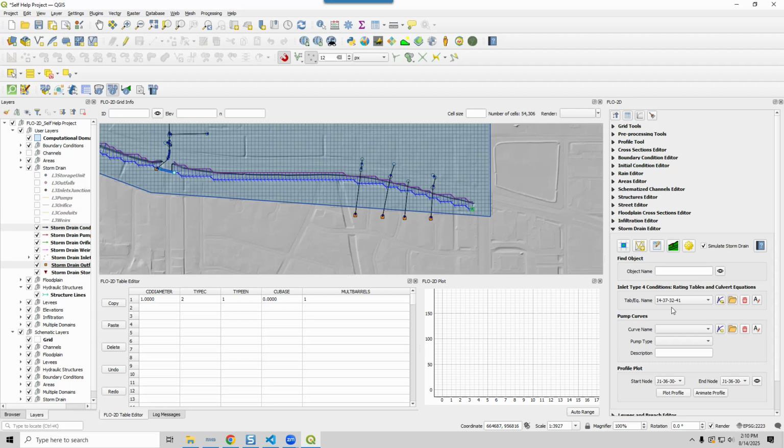And then if you do this one, it becomes like a generalized culvert equation, but of course with your conduit, there are certain things you don't need, like your conduit diameter and things like that. So multiple barrels. This would be the width. If you set this type equal to 2, then this width becomes a 0, because it's a diameter, right? Entrance type, this is 1 for box culvert or rectangular culvert and 2 for circular culvert.